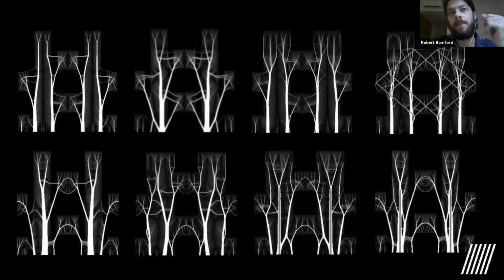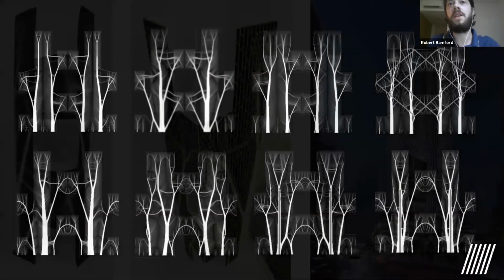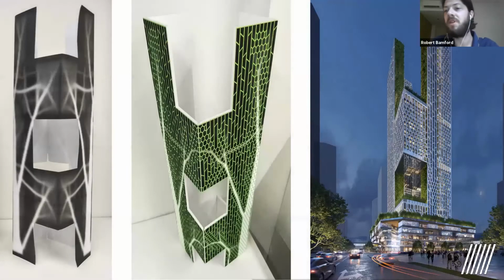So this is an unwrapped elevation of a skyscraper as it happens, and we're looking to use these sort of topological methods to find efficient material density and what we call heat maps, so that we can then inform ourselves and then recreate framing using strategies that can be built and can be realized. So of course, this is how nature would build the building, but we have to modularize given the current situation we have with technology.